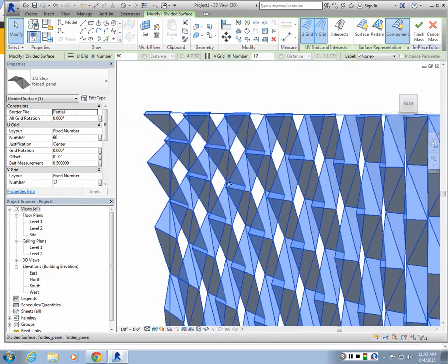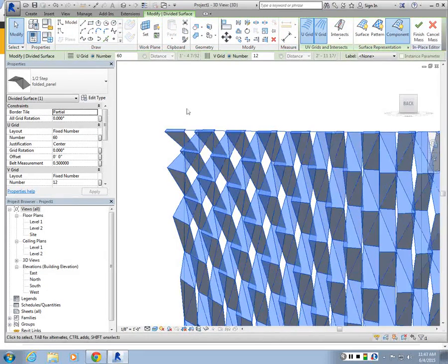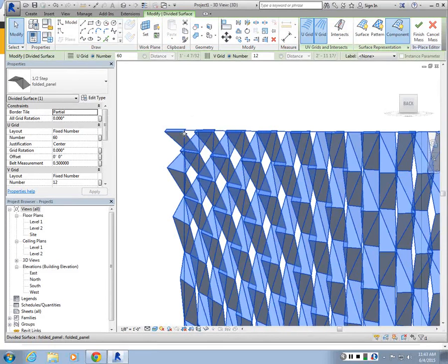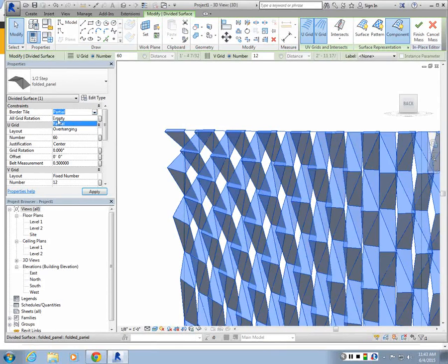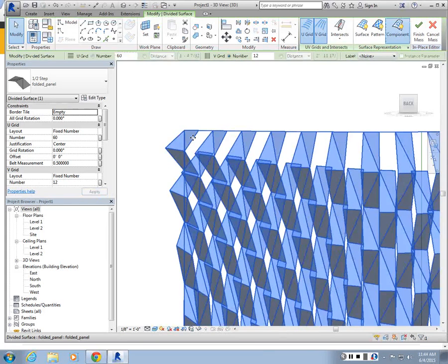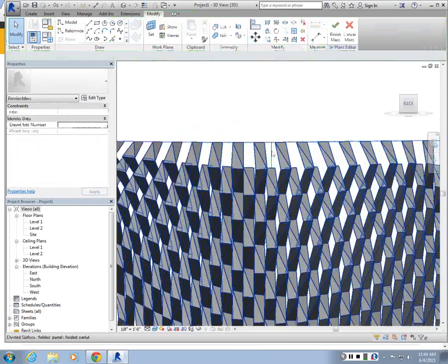What Revit is trying to do is basically extending the surface and assuming there's a half tile there, or tries to visualize the tile that it can place there. So if you make it empty, hit apply, you're going to see all the border tiles being removed. So now those are basically taken out, right?